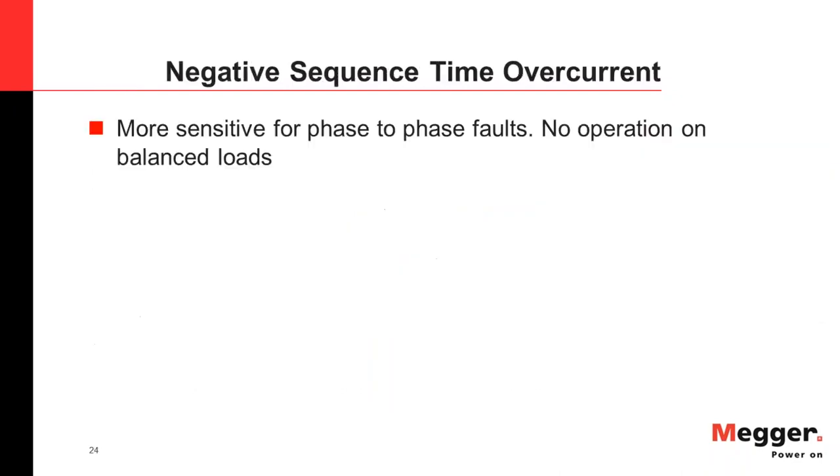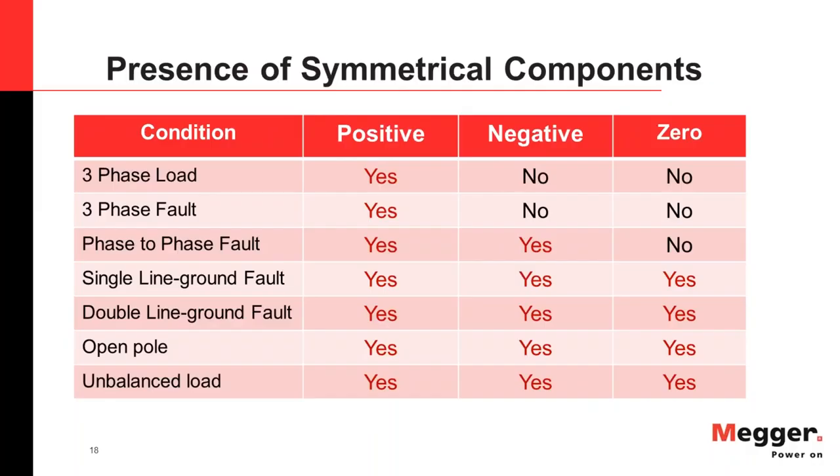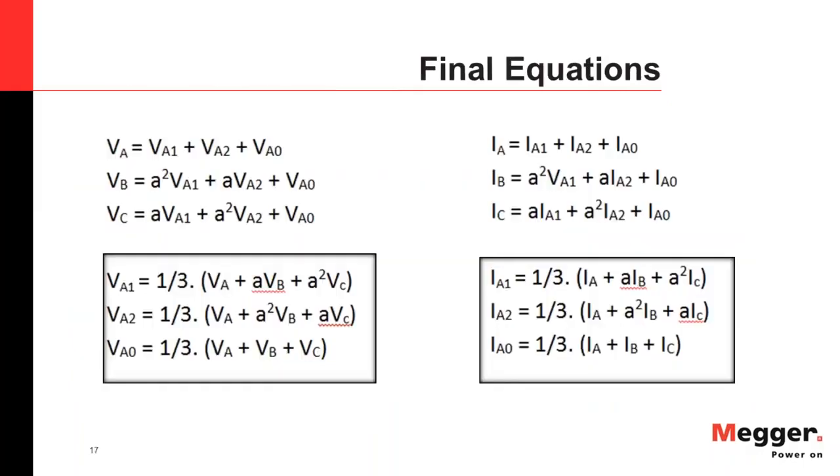It's not actually monitoring your sequence components. So you need to provide phase values to the relay in order for the relay to internally compute everything. That's how it is done. So yeah, you are absolutely correct on that.